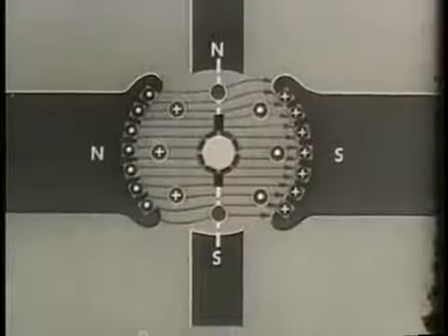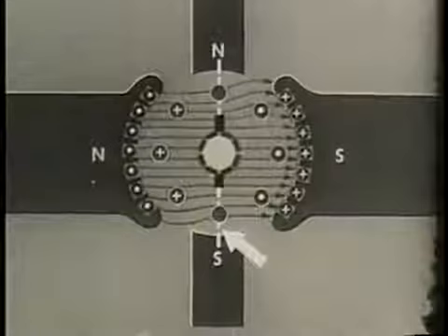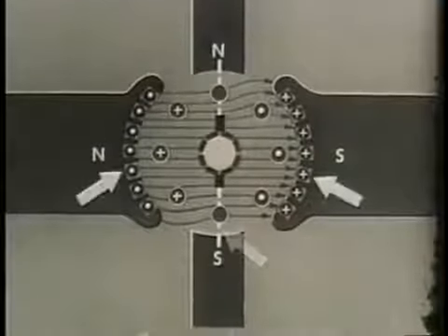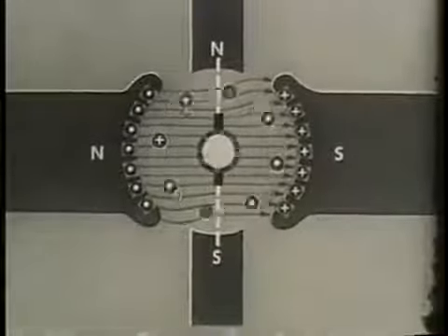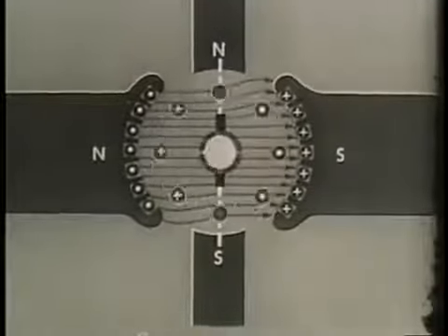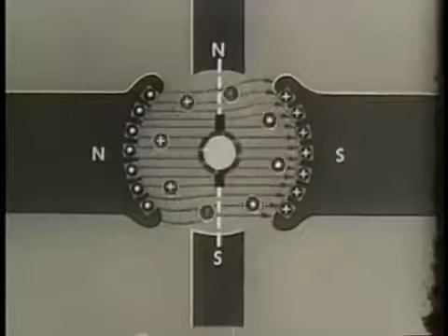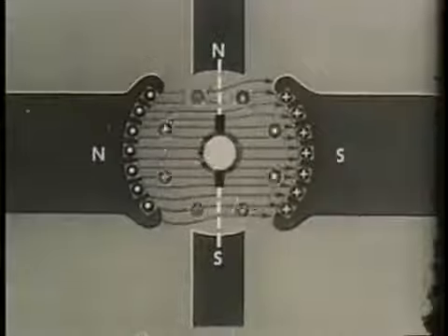The neutral plane is moved back toward its correct position. Also aiding are compensating windings, which carry armature current in the opposite direction to the current in the armature conductors. The neutral plane is thus maintained in its proper position. DC motors operate most efficiently when sparking is eliminated.